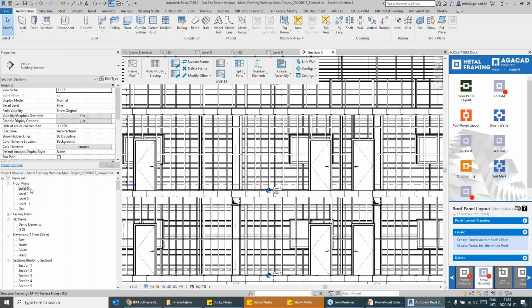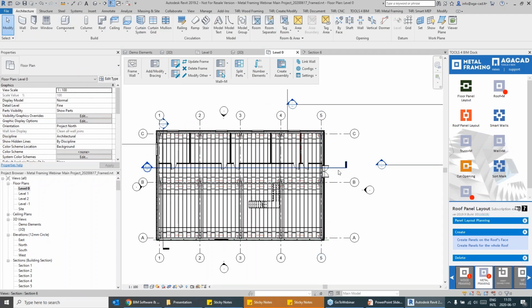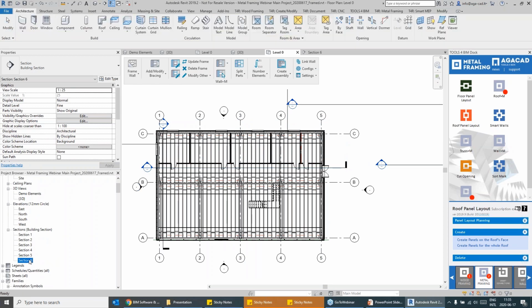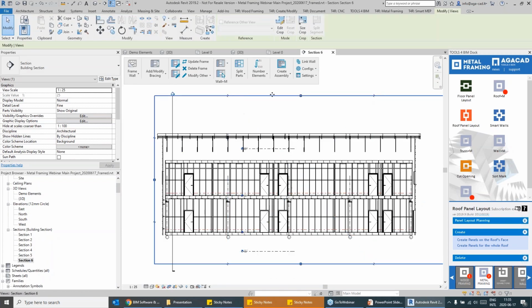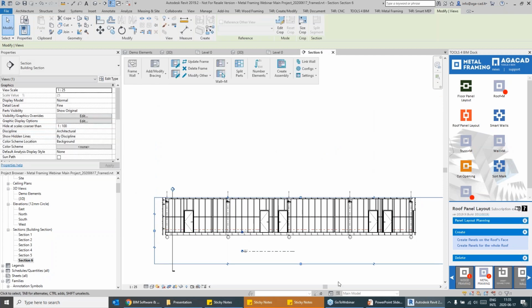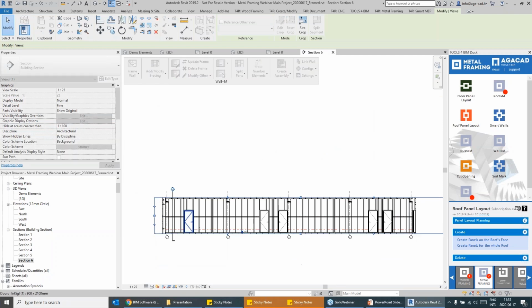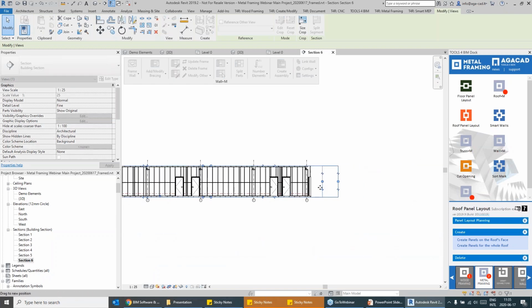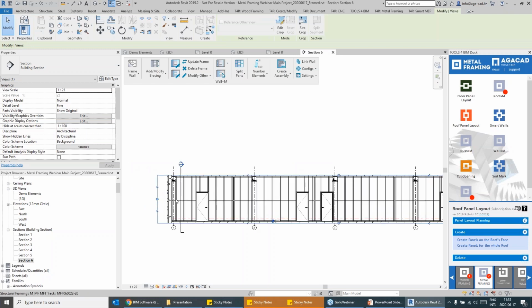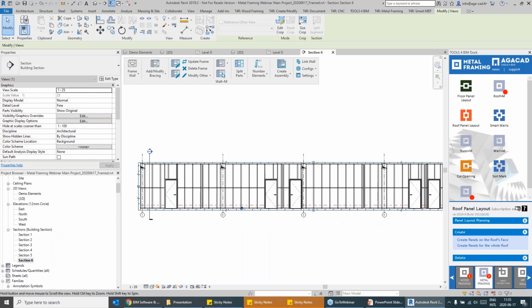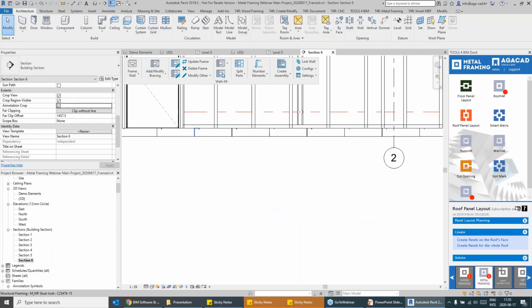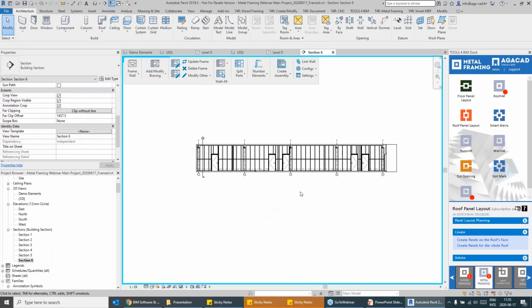Oh, maybe I'm seeing too much frame here, so let's just adjust my section a little bit. And whenever I'm back to that section with just those frames, I can also adjust it to show just my first floor where I didn't split my wall into panels, so maybe this will not fit into my shop drawing sheet list. So I can just go and adjust this view the way I like. And let's maybe also hide those elements for now.